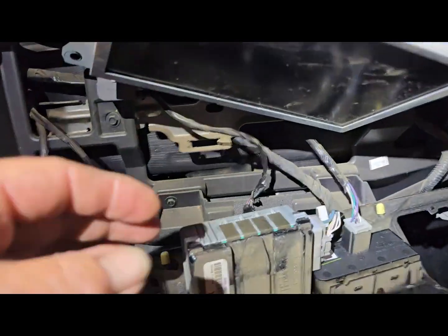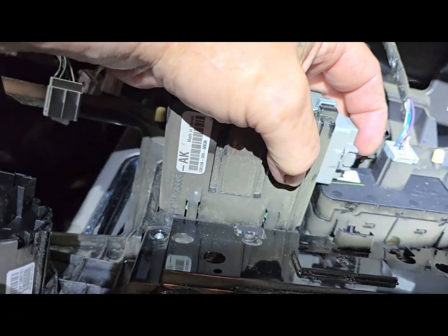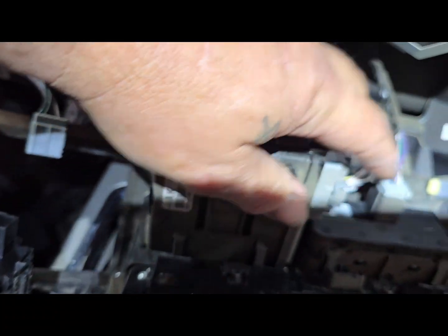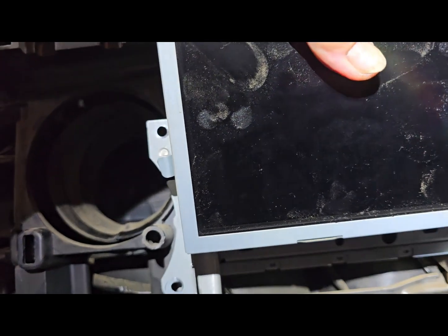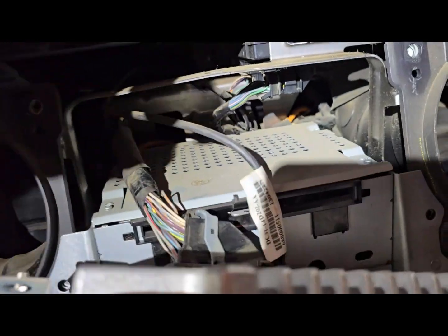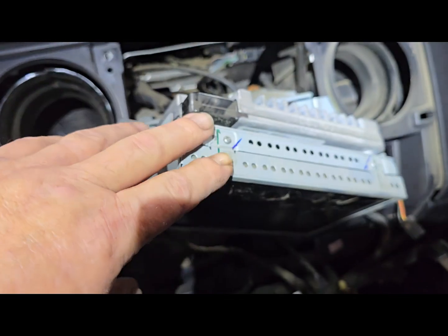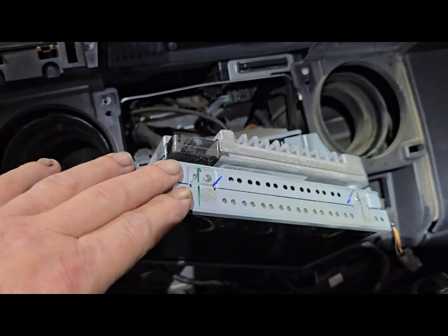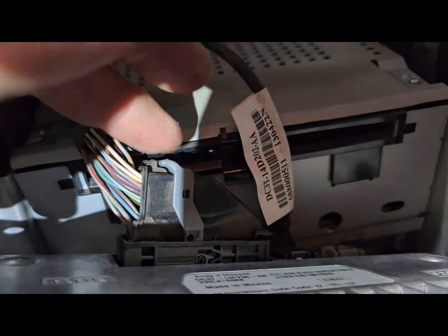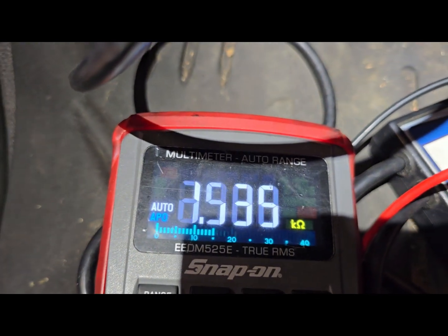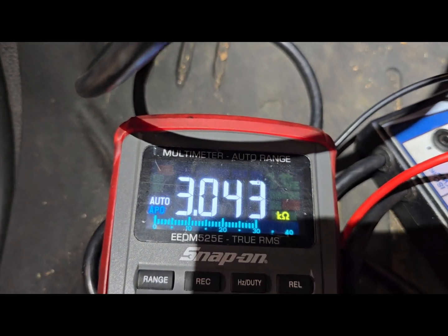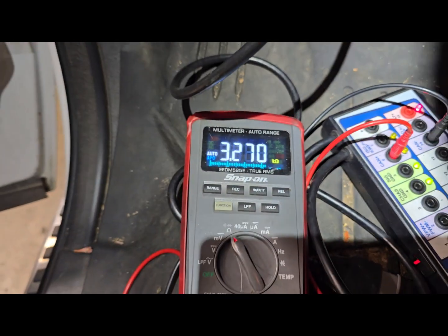All right, so I connected the trailer brake control module. Have not turned the key on or anything. Still had 33 ohms. All right, that's connected. The next thing was the APIM. Now, this was my initial suspect. Found something online that said these are common to fail, and so I connected. This was the first thing I disconnected, aside from the PCM and the TCM. So I connect the connector here, and now you can see that I have 3,000 ohms of resistance on the CAN system.